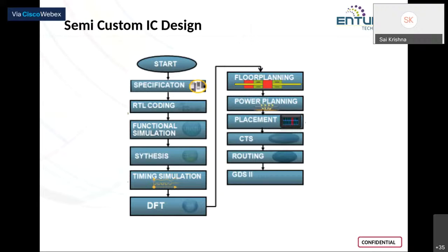Okay. So as I was saying, in VLSI, when you want to develop a design or a chip, you follow a six-step procedure where the first step would be realizing your specifications. What is it exactly that you need? Under this specification, we talk about two things. The first one is your functionality part. How exactly does your design work? For a given input, what is the expected output? And the second part is relating to your physical aspects, such as the area occupied by your design, or the maximum power dissipation, or the response time, etc.